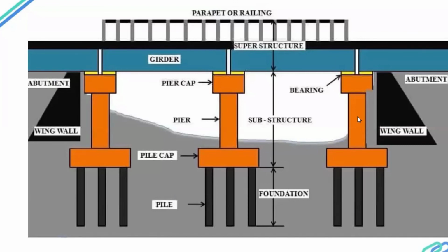and all those things. And then they come up with the problem that they cannot do the piling at that particular location, the location that the consultant or the designer has provided to them. So then as a designer, you need to come up with alternate piling locations, alternate pile configurations, which would require you to design a non-standard pile cap. It could be a pentagon type of pile cap or a hexagon type of pile cap. It could be a different shape altogether. So all those are the challenges which we come across during the construction of the pile and pile cap, the foundation part.